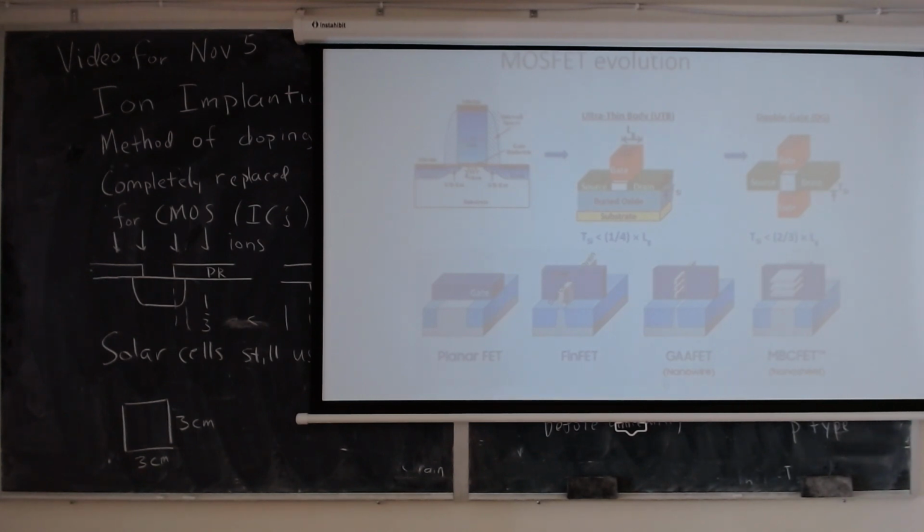The gray area here is semiconductor, so you've etched it to form a ridge, and now this is your channel, not planar anymore, but vertical above the surface of the chip, and the gate is wrapped around it so that you can make basically the gate smaller. So we've changed our technology from planar FETs to FinFETs, and this is projecting even further variations going forward.